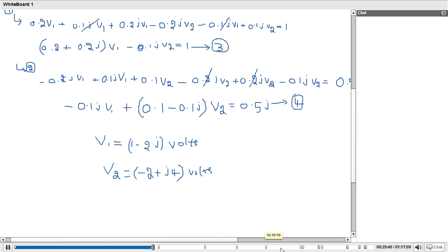No, not like that. So those are all imaginary values. 0.5j is nothing but 0.5 at an angle of minus 90. So just write it as 0.5j. Think of those only as values. The current is also a complex quantity here in this AC circuit. The current and voltages may also be given as complex quantities. Complex means a plus jb. A complex number is nothing but one consisting of a real and an imaginary part.